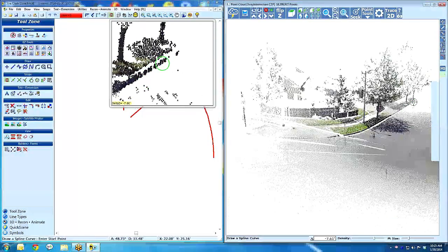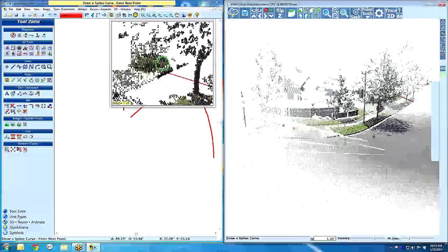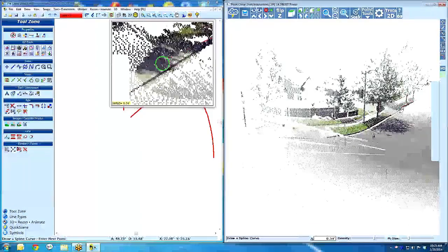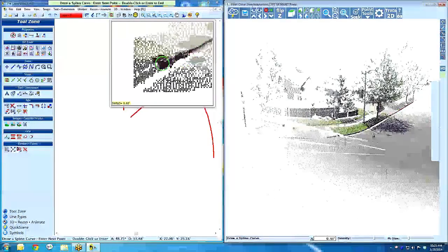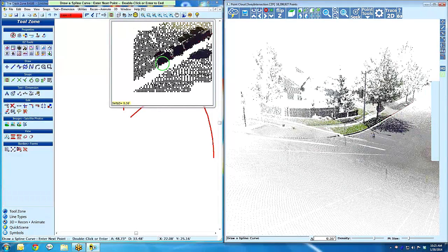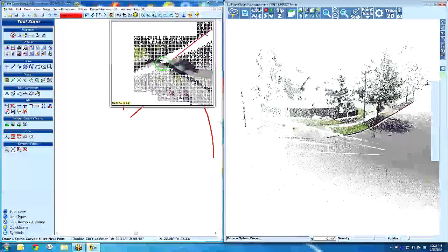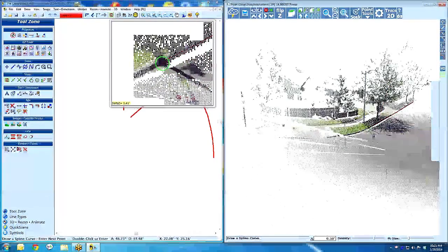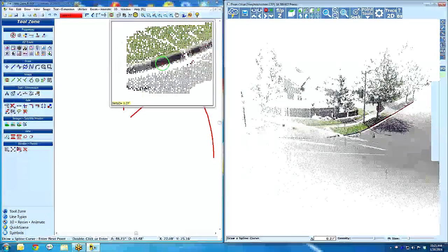It kind of washes them in there. So I'll start all the way at the back end there. And if you look on the right side of the screen, you can see where I've started the curve. But all I have to do is use the right side to kind of line up, and then use the mag window to get that red dot right on an edge. So now, and you'll notice if you look down in the lower left corner of the mag window, the delta Z is also displayed. So in case we were to hit the tree here, you'd see the 17 feet, and you'd back off on that. So I'll move in right to that edge here, and then I'm going to start the curve on the edge.